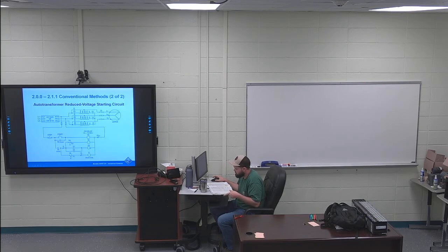The normally closed auxiliary contacts of 1S in the control circuit for contactor R open. So R opens up, 2S is closing. This provides an electrical interlock to prevent contactors R and 1S from being energized at the same time.